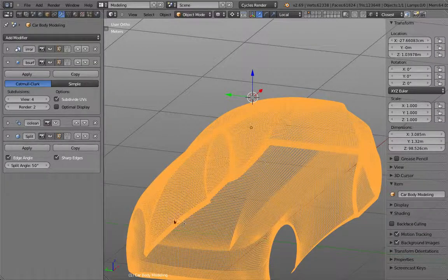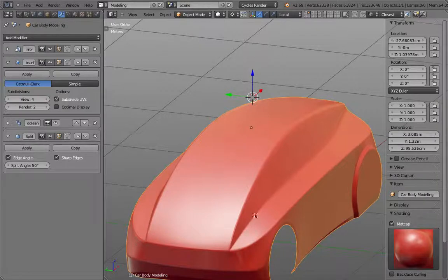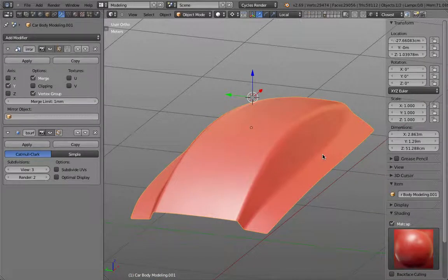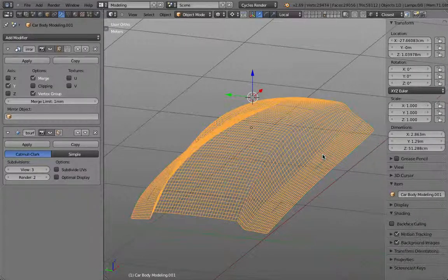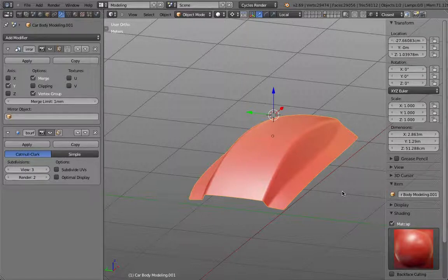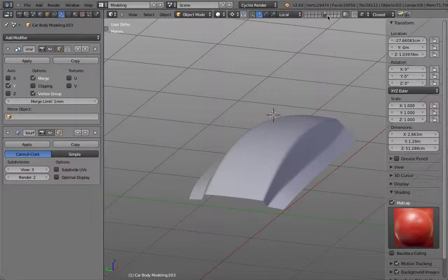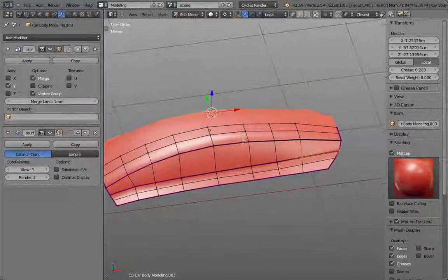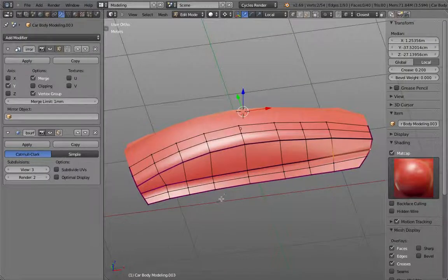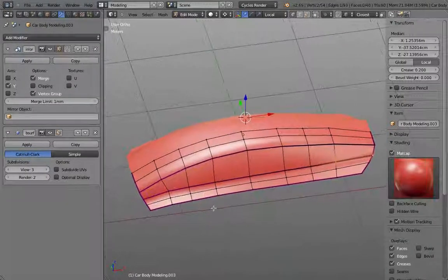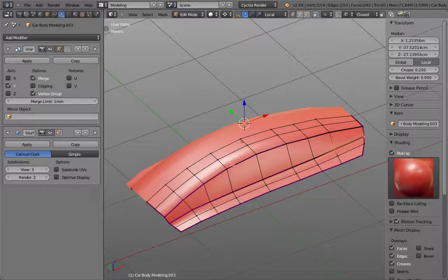For example, all those meshes in between I don't really need because all I need are just loop cuts along those crease edges. And this actually brings me now to the second workaround, which at this point might be a little bit more efficient. So for example, let me move this one onto a different layer. So instead of using this creasing, I simply start beveling those edges and then scale those sections separately.